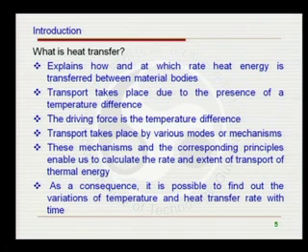For any transport to occur, whether it is momentum transport, heat transport or mass transport, there should be some kind of driving force. In the case of heat transfer, the driving force is the thermal potential difference, which is nothing but temperature difference, as thermal potential is measured in terms of temperature. This transport takes place by various means: conduction, convection and radiation are the three basic modes of heat transfer. We will enter into these in detail a little later.